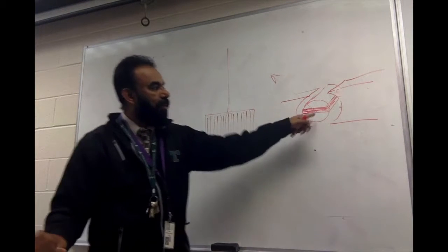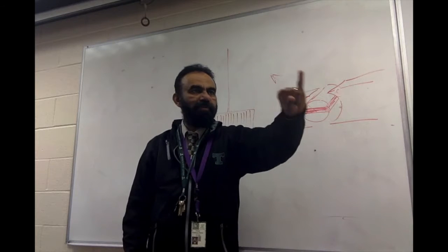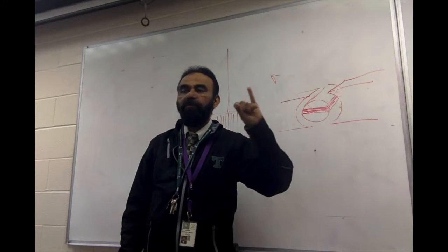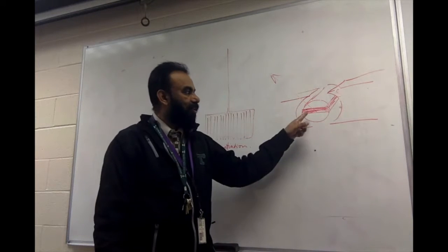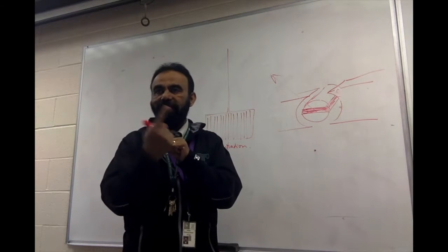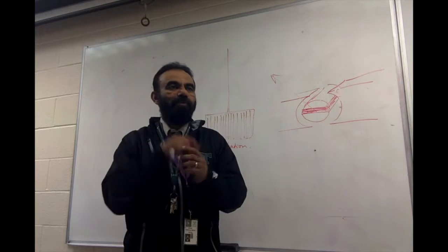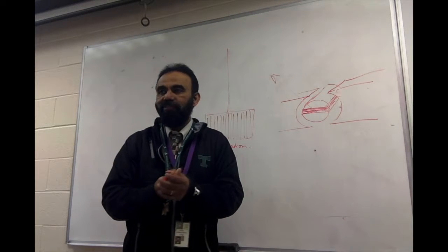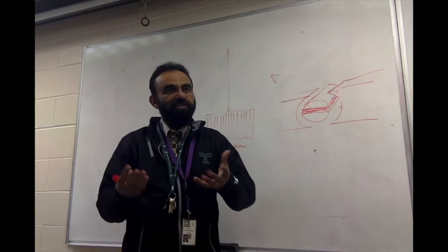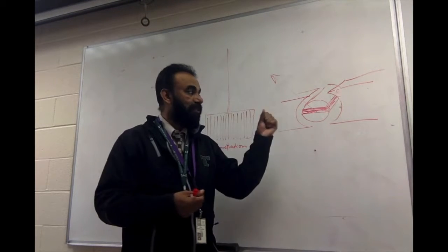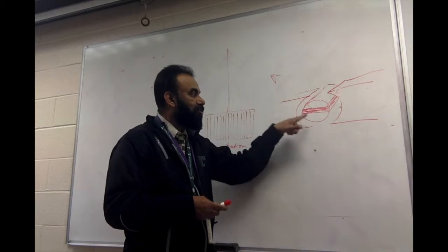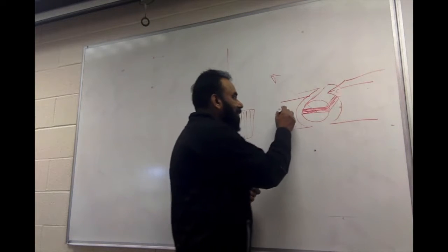So what's the purpose of the core? Number one purpose, someone said it here, is to provide mechanical strength or stability. So the coil, instead of winding the coil in the air, it is better to wind it on something solid, so you'll have more inertia and more strength, right? That's one purpose. The second purpose is to strengthen the magnetic field.